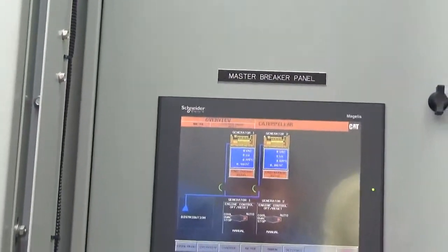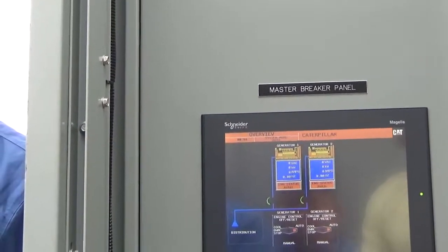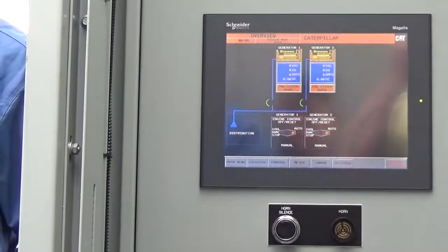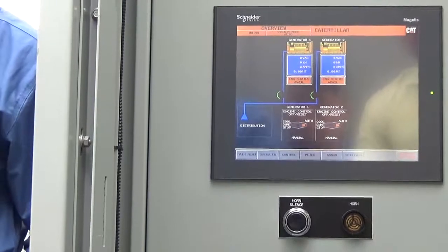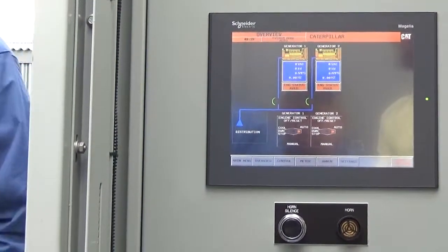That's good, because if we only show first and last, we don't show the progression like he does. And I did see that one said on 10-3 it had a non-auto alarm. Yeah, because we took it out of auto. We couldn't get it to clear, even though it wasn't an alarm anymore. So the display said take it out of auto to reset the alarm and then put it back in auto.